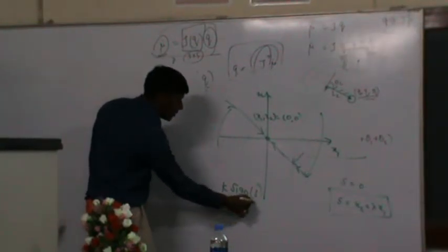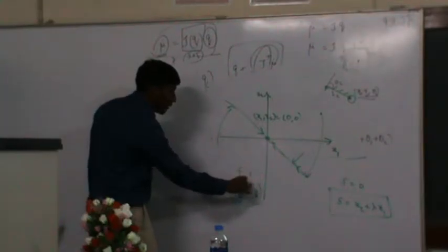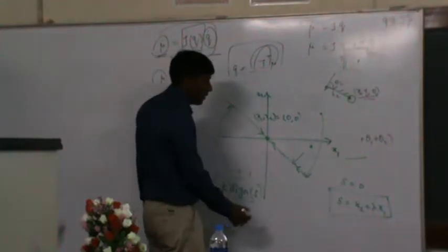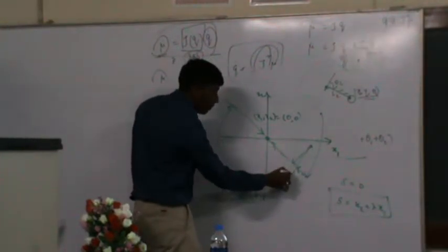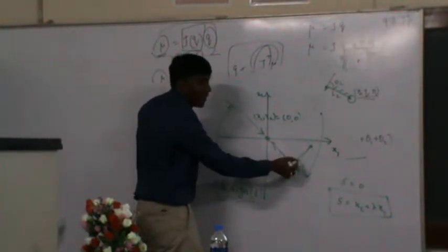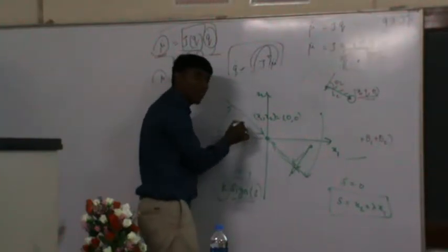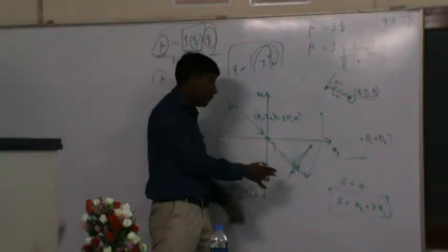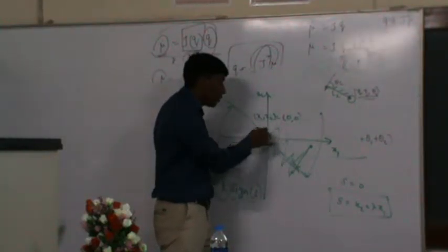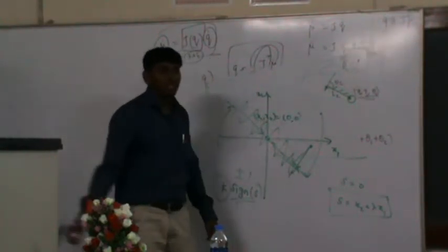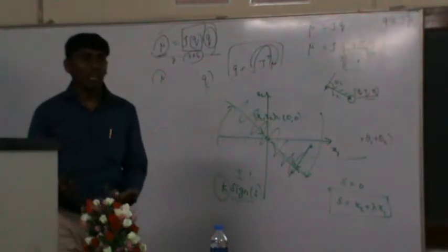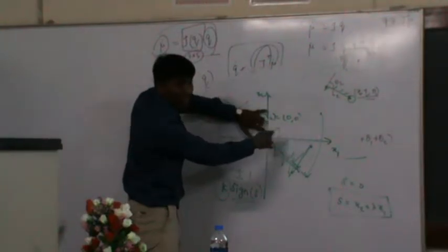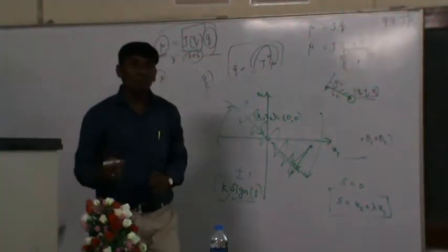So this sign of s is actually going to give plus or minus 1. So this k will make sure that if I have it here, it may go here also, then it will come back. As per the theory, it will come and hit and it will follow. But in reality, it may not stay there. It may come and go to and fro. It will start chattering. This is the problem we end up with. Probably it will not extend, but it will start chattering here. So this is the problem.